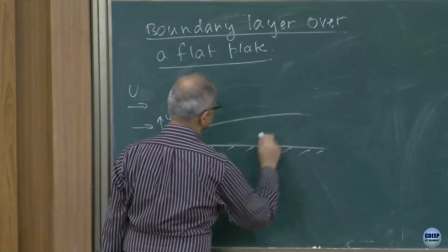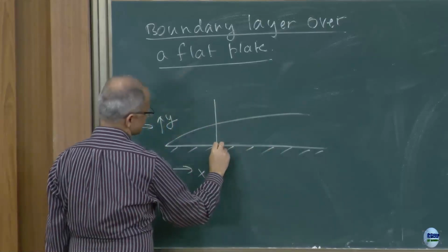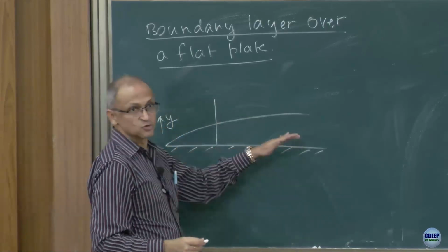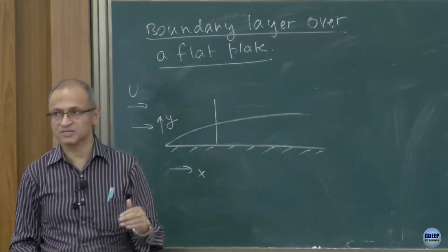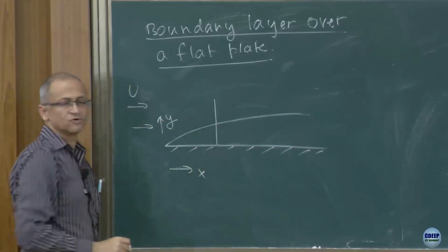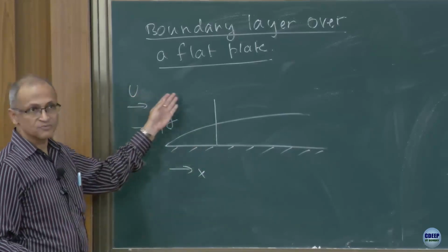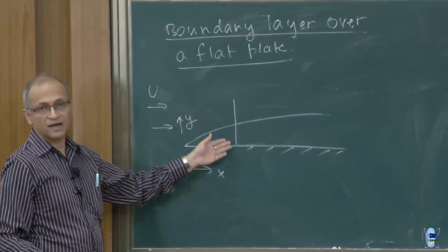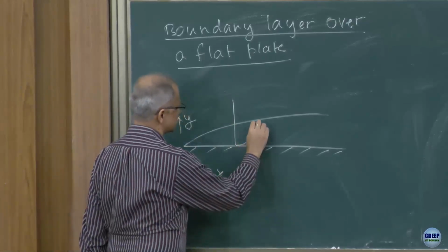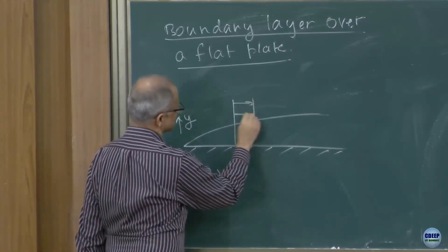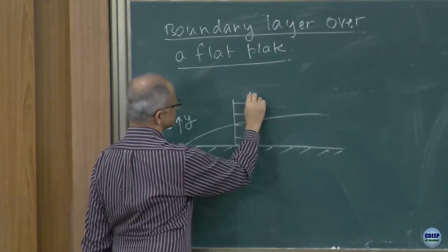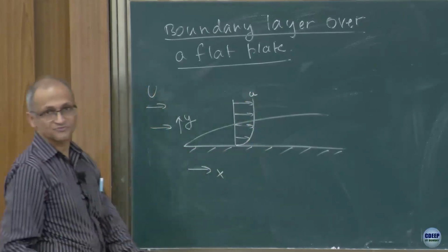Now, what exactly is a boundary layer? The boundary layer means that at the surface, we know that the no-slip boundary condition has to be satisfied. The flow will go to zero velocity here. There is going to be a velocity of capital U far away from this surface. And therefore, there should be some gradient, which is taking me from zero here to some finite velocity, capital U, far away from the plate. So this is how the velocity distribution would be. We call this the velocity profile.